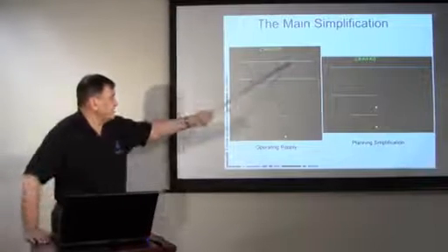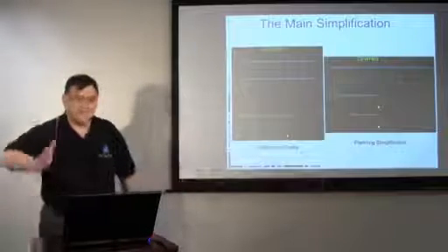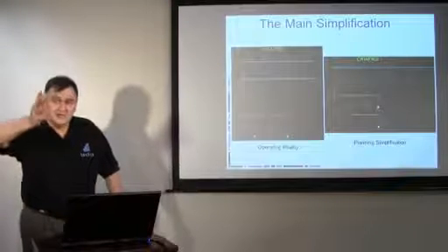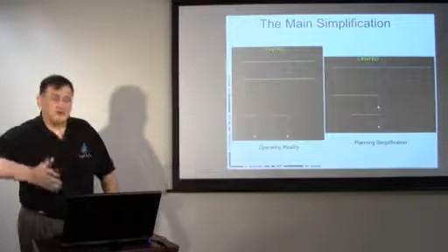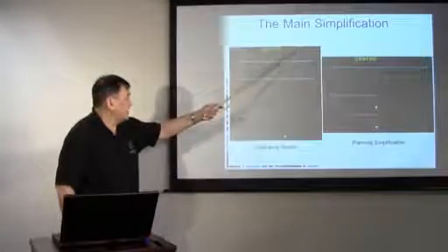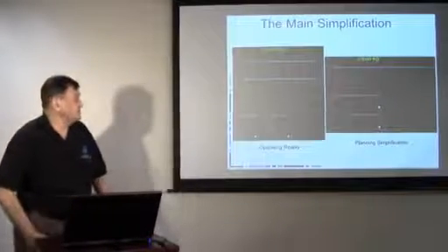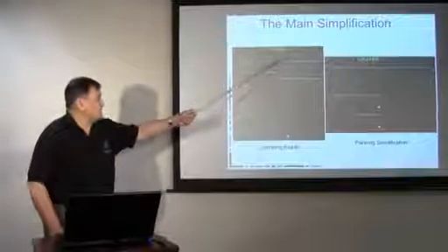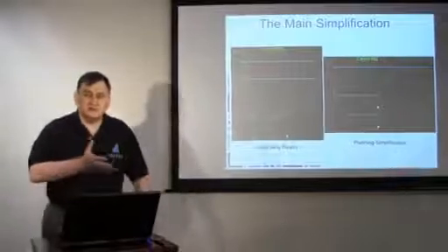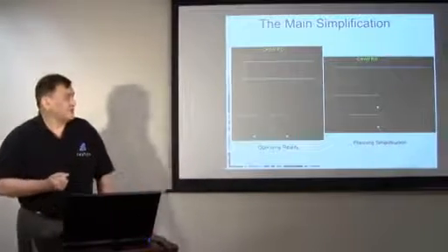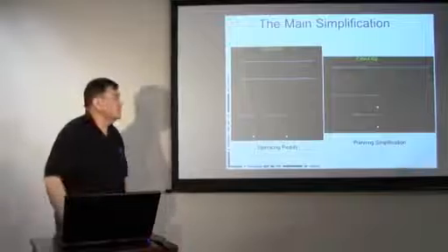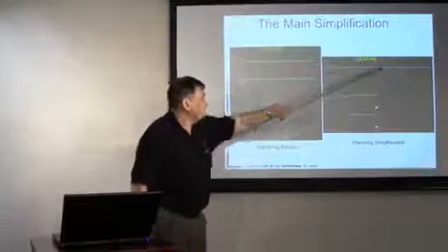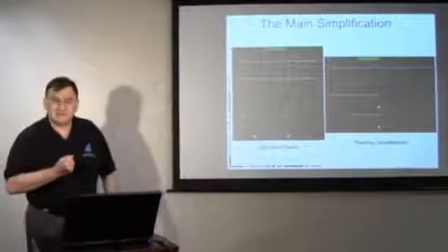Even though this is a single phase, the operator says that circuit breaker will actually be 3 separate units, but they can relate to the fact that we've taken the 3 phases and converted it down to what we call a single line diagram. We have one line representing each of those 3 phases. But what we do in the planning model is we literally condense all of that. We ignore all the actual breakers and all the circuits, and we say, let's define a bus. And that bus is really an abstract view of the world.